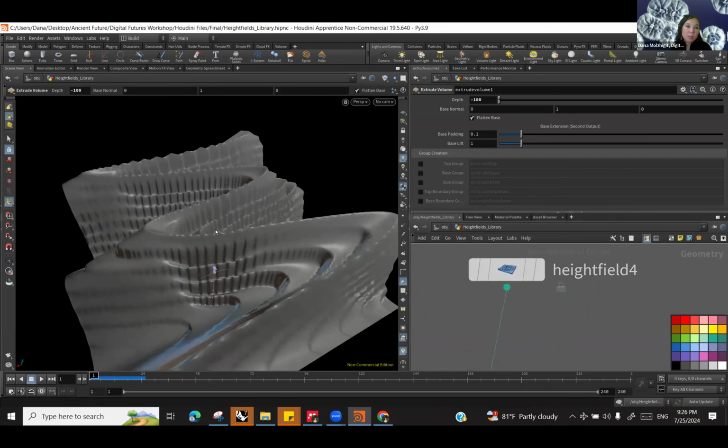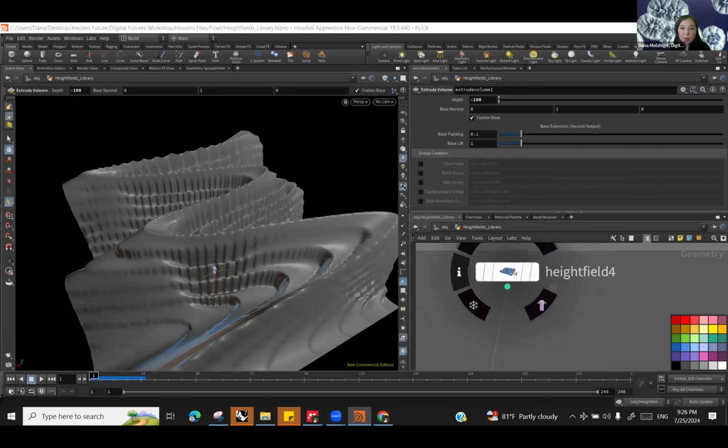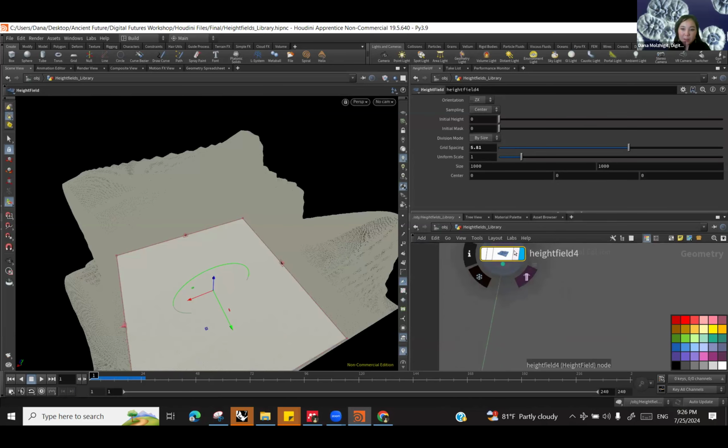But Houdini is not precise like Rhino. It has its own unit systems. In height fields, it's similar to meters. I think 1 voxel is 1.2 meters, if I'm not mistaken. So a 1,000 by 1,000 grid of voxels is almost 1,000 by 1,000 meters, but it's not precise. Okay, the last section, very fun.